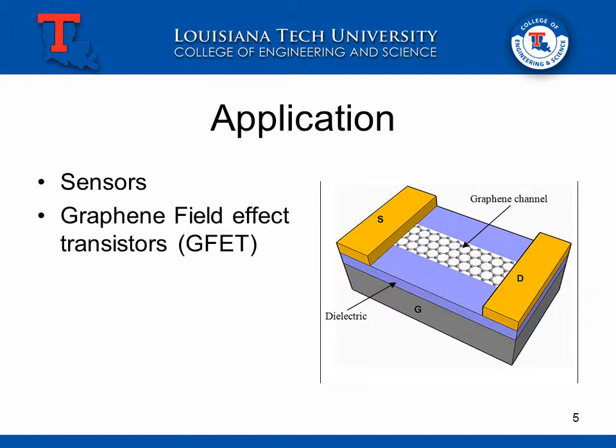One of the disadvantages of graphene transistors is that they lack a band gap, which means they do not have both on and off states, and even at a density of states of zero value they cannot turn off completely. Therefore, graphene cannot be used in digital switches. However, due to its unique carrier mobility properties, its thickness, and its stability, it can be used in fast analog devices like radio frequency transistors.